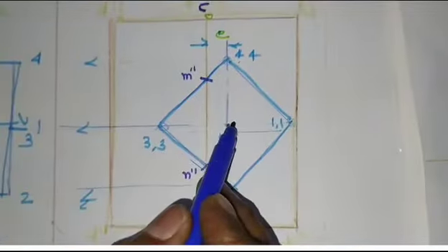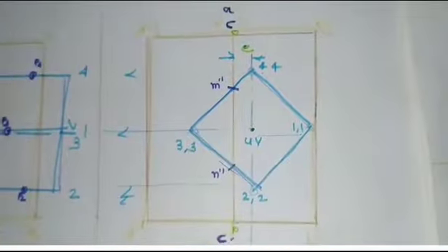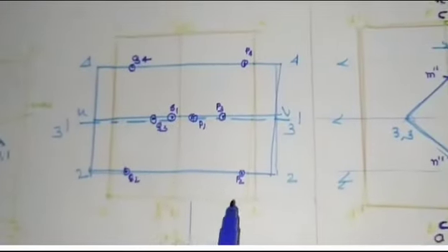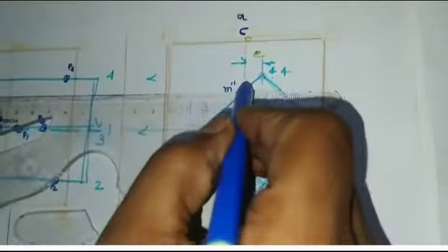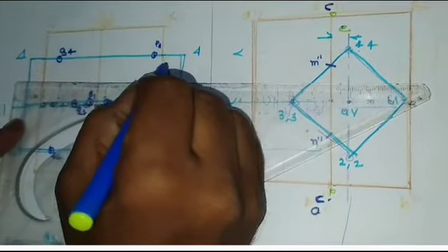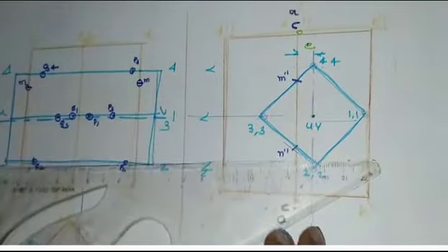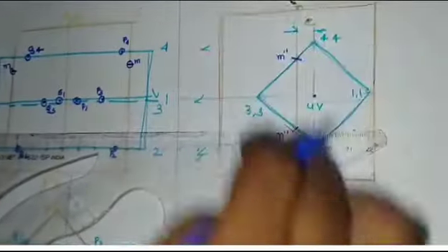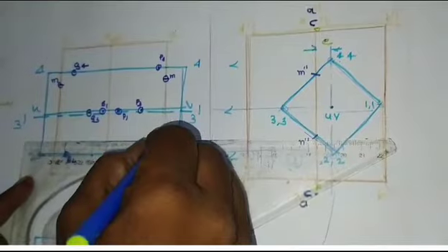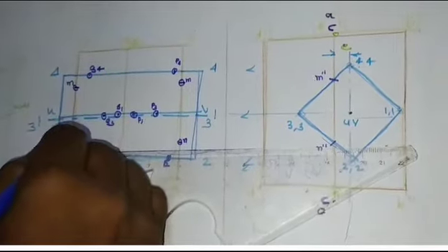Now in the second figure, eccentric without crossing the boundary, two points are added here, M and N. M and N lie on AA and CC. Here is AA in front view. This is the CC. So I will transfer this point where this point lies on AA and CC. This is AA. So I will name it as M. This is the point M. Here N. N also lies on AA and CC. This is the point N, and this is the point I have transferred.